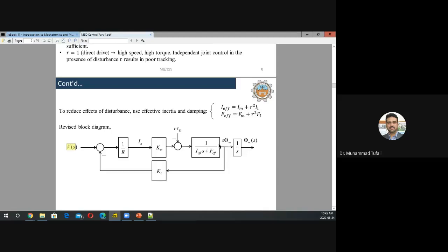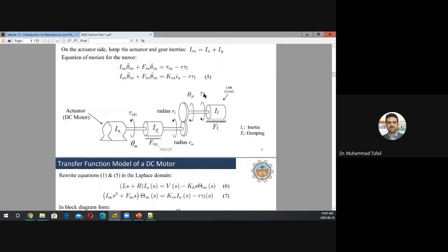Normally imagine, whichever motor you use to drive a load, the size of the motor is much smaller than the load would require. So far you have only driven a wheel with a motor, that was the whole load, and on the wheel there is a disturbance because it is continuously in touch with the ground, so there is friction there too, but those were the only torques that you have encountered. One is in order to give it a certain acceleration, that's inertial torque, that was your tau L, and one was the friction torque that's coming from the contact point between the wheel surface and the ground.